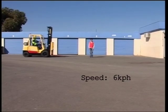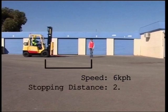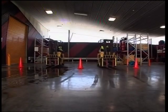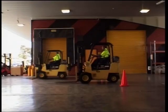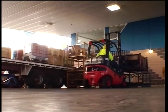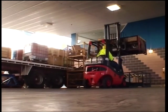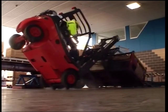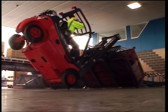Even when traveling at 6 kilometers an hour, it will take you 2.9 to 3.2 meters to come to a safe halt. This distance may double if you're distracted or traveling on a slippery terrain. Accelerating backwards too quickly can cause the center of gravity to move outside the stability triangle, resulting in a forward tip over.